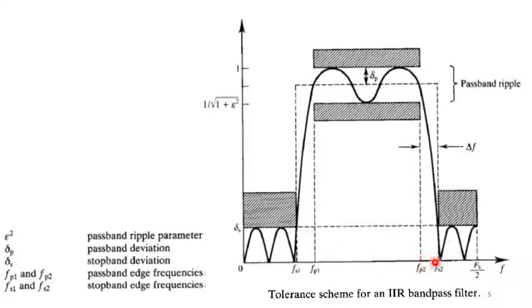Also the third thing is the transition band. In the practical case, we also have a transition band, which is the difference between fp2 and fs2. So this represents the transition band. Similarly, in the case of a practical band pass filter, how many bands do we have? The stop band, transition band, pass band, again a transition band, and a stop band. Whereas in the case of the ideal filter, we only have stop bands, so there's no transition band.